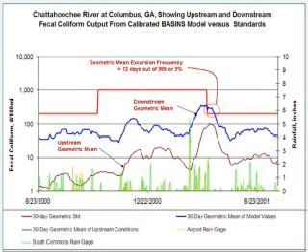Same thing with digression. A digression is when a single sample maximum, which is typical in water quality standards also, is higher than the water quality standard. And again, an impairment or an exceedance is only when digressions exceed the frequency allowed in those criteria. And it only takes one exceedance to cause an impairment.